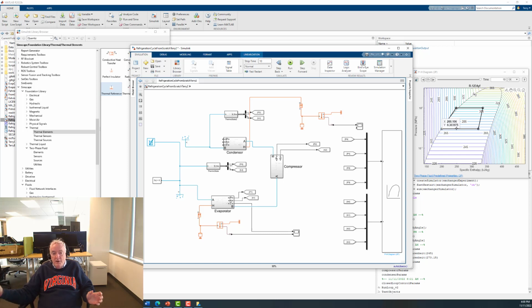If it's pure vapor, it's not going to have the ability to absorb heat at the rate you need. But if it's pure liquid, it's not going to have the volume in these heat exchangers to expand the fluid as it converts from liquid to vapor, to achieve the greater specific volume, or let's call it the lower densities, that the evaporated fluid will take on.